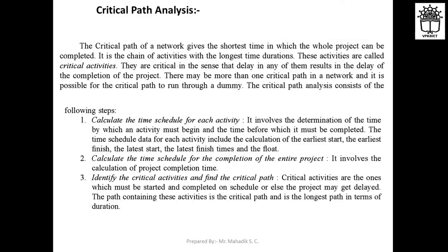So let us see with the help of one numerical how to find out the CPM, that is critical path method analysis, right? Consider the network shown in the figure at the bottom, which consists of the following activities. The activities and their durations are given. In this case the network is also given, because the preceding activities are not given, so there is no need to draw the network. The network and the durations are both given. So for activity 1 to 2 the duration is 15, for 1 to 3 the duration is 15, like that. Okay, it is just in weeks, right?